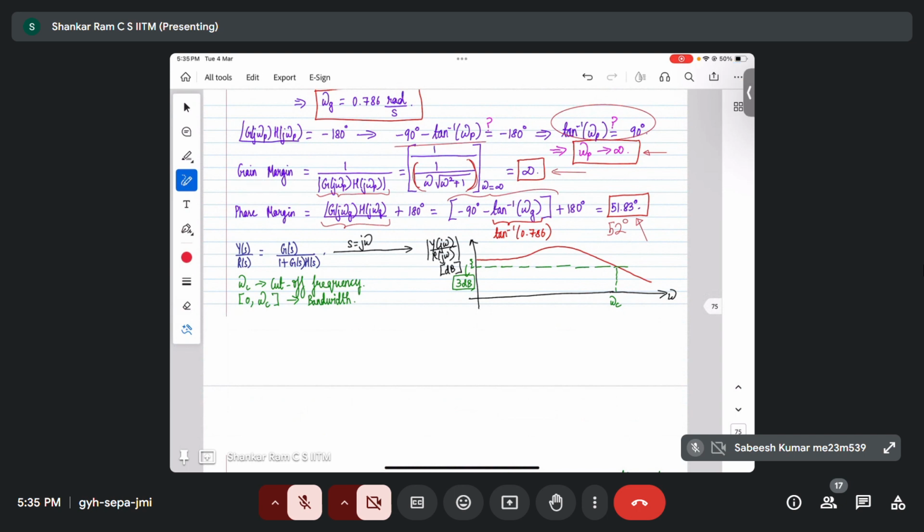Sir, is there any limit set to say that this much margin is great? For gain margin, it is understood that infinite margin is the best. But for phase, what values should it be? Once again, the designer specifies. Sometimes people will say I want a phase margin of 30 degrees or 45 degrees. So around that ballpark is what people will typically specify.